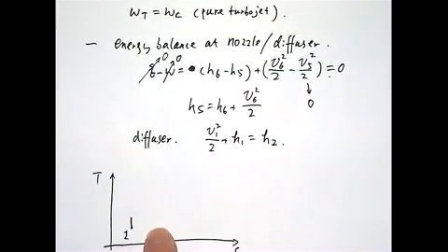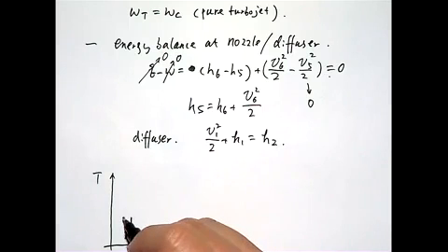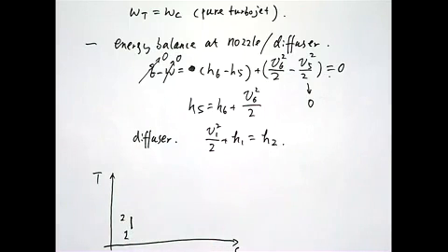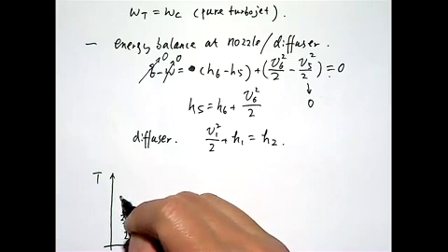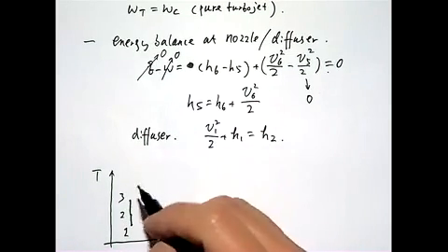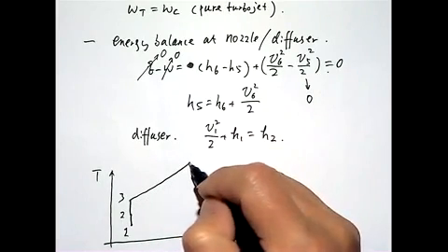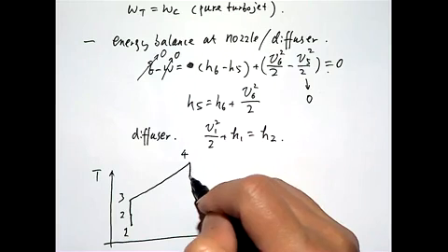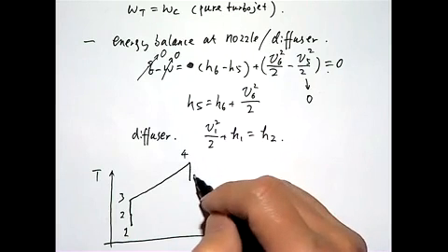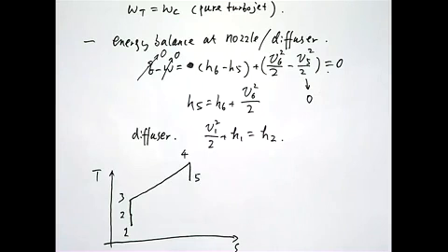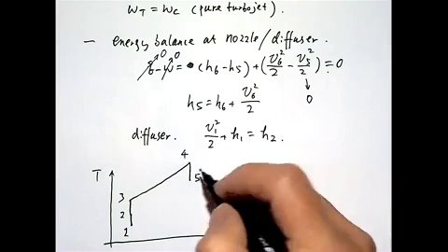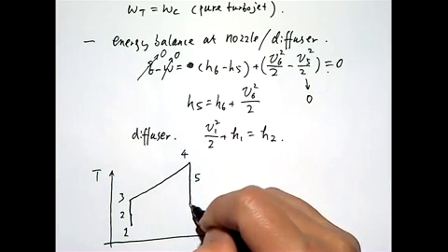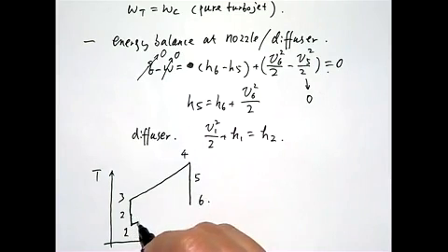So we have a vertical line. That process is isentropic to state 2, and state 2 going into the compressor is again an isentropic process. So we keep going on this straight line to state 3, then into the combustor to state 4, then going down through the turbine to state 5, and then entering the nozzle. Again, the nozzle is an isentropic process.